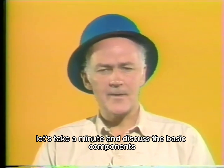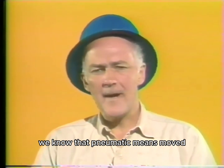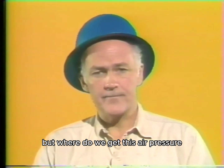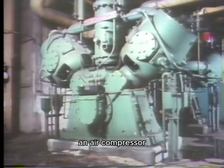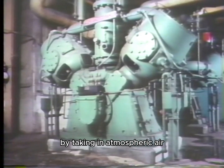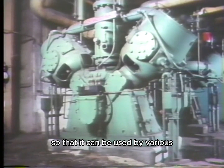Let's take a minute and discuss the basic components generally found in a typical plant's pneumatic compressed air system. We know that pneumatic means moved or worked by air pressure, but where do we get this air pressure? The first component typically found in an air pressure system is an air compressor. An air compressor functions to increase the pressure of air by taking in atmospheric air and squeezing or compressing it into a small space. This increases the energy of the air so that it can be used by various equipment